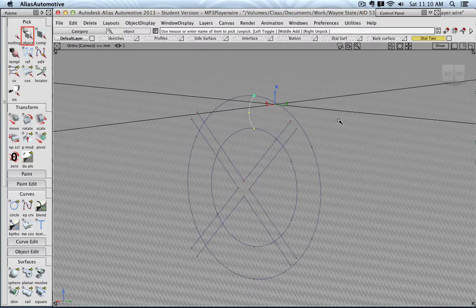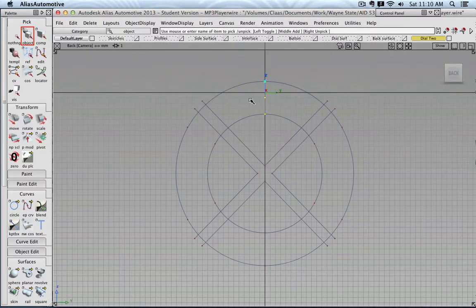So before we create the different surfaces, we have to prep the profile a little bit further. For example, this curve is basically at the center of a button. I would like this curve to be here, so that means I have to rotate it over 45 degrees. And an easy way to do this, because this whole sketch is very symmetrical, is to move the center point to here, because then I can rotate in relationship to the center point by 45 degrees.